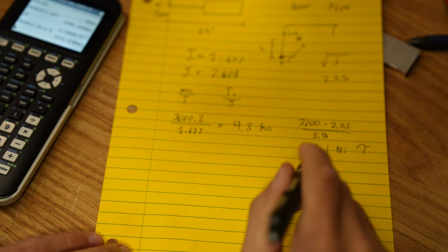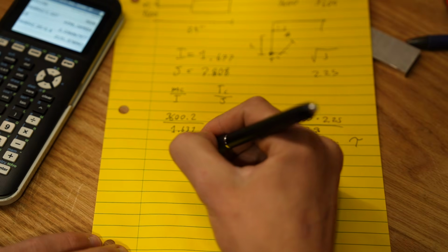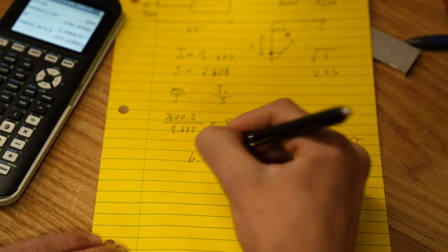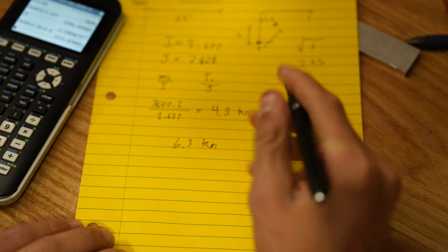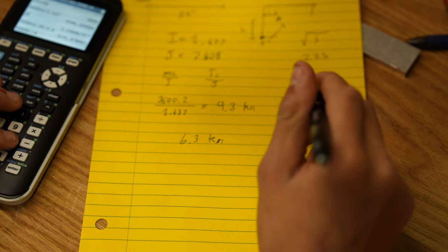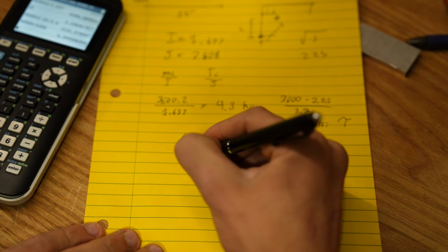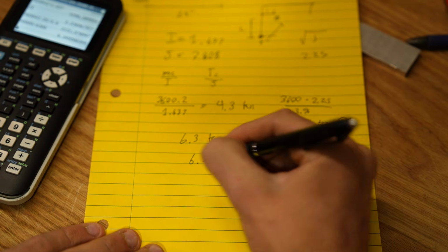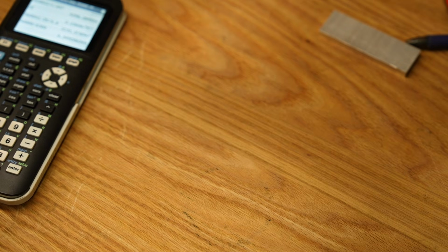We're going to use the adding them together trick, which is a better name out there. And we get an equivalent stress state of 6.3 KSI, which if we calculate for aluminum, 40 divided by 6.3, we get a safety factor of 6.34, which is great. So box tube, that is.